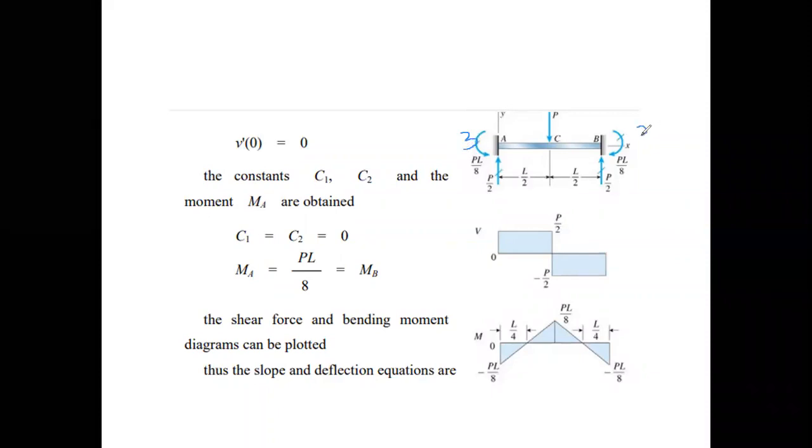Three support reactions are over here. So the basic indeterminacy in this case is 3. We can clearly see at this end the number of reactions is 3. Also at this end the number of reactions is 3. So we just need to calculate it like this. Total number of reactions is 6, and 6 minus the equilibrium conditions, and the equilibrium condition for a 2D frame is 3. So the total indeterminacy in this case is 3.